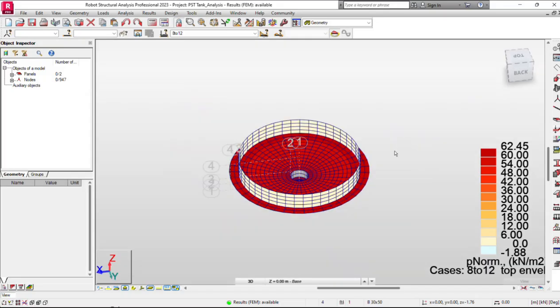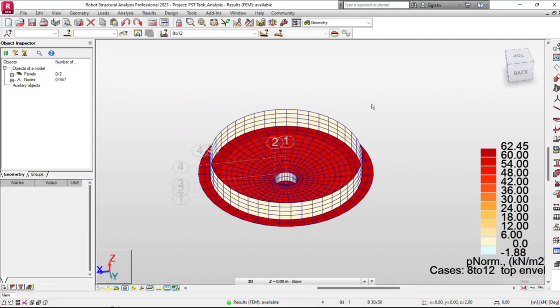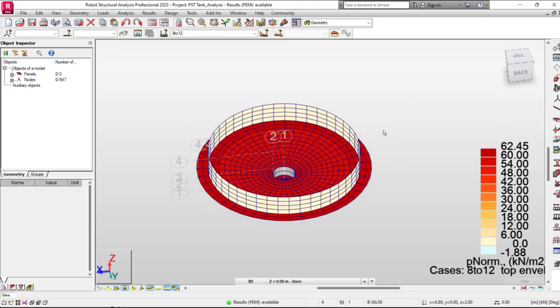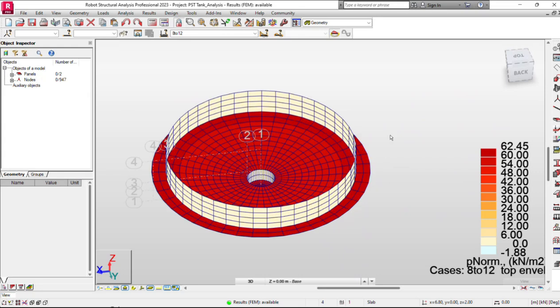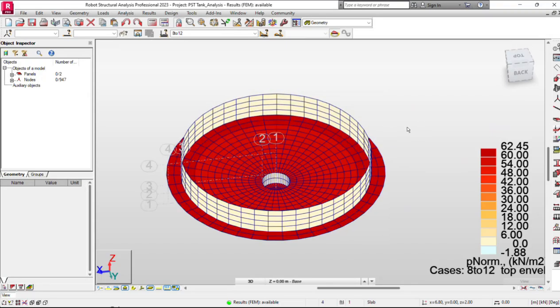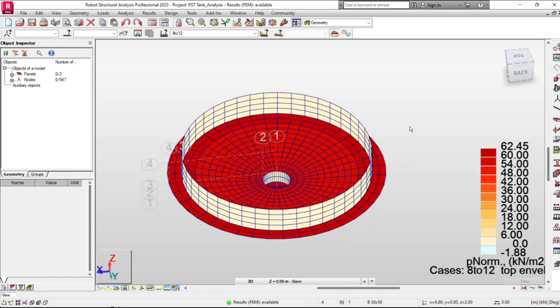Next we are going to check for the displacements. Remember that we've set a maximum of 25 to 50 mil basically for water retaining structure, but this is a type of, let's say, water containing structure because it's a preliminary settlement tank, so it contains sludge and water. According to Eurocode, it's around 25 mil to 50 mil maximum. That's the total displacement. All right, not the differential settlement. I believe that differential settlement here is not that critical, but we also can check it.